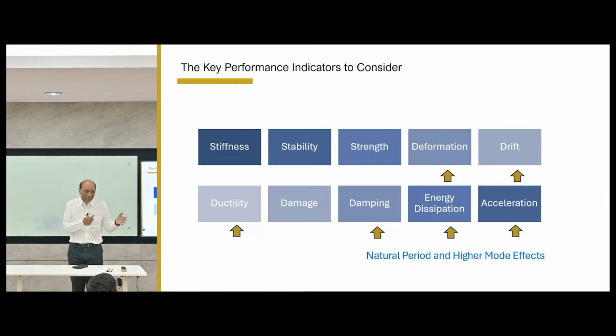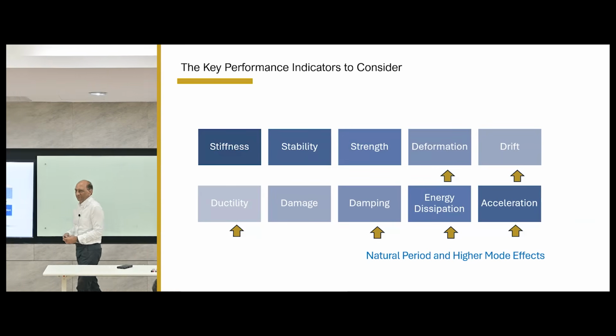If we control the heart rate, which we can, then we will be able to control these things also, right? How can we control the heart rate of the structure? There are only two things, mass and stiffness. So if you want to control it, you either change the stiffness or you change the mass. Those are the only two possibilities, right? For human beings, you exercise, you get fit, your heart rate will become better.